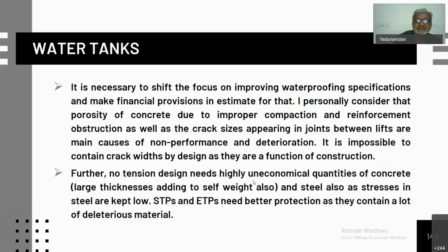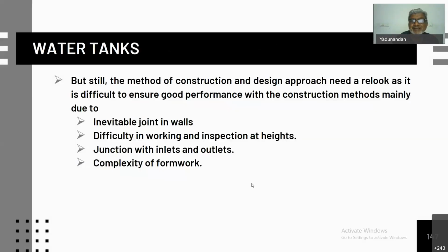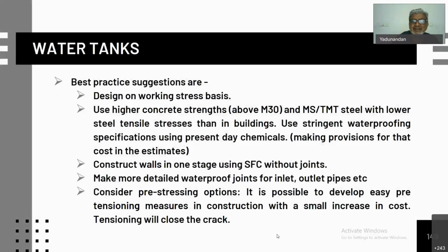But I am of the main opinion that it is necessary to shift the focus to improving waterproofing specifications and financial provisions in the estimate for water tanks, because it is difficult to ensure good performance with the construction methods, mainly due to the way the tanks are constructed. You have to consider lifts and inevitable joints in the walls. There is difficulty in working and inspection for tanks with staging, and we have junctions with inlets and outlets and complexity of formwork, so that the